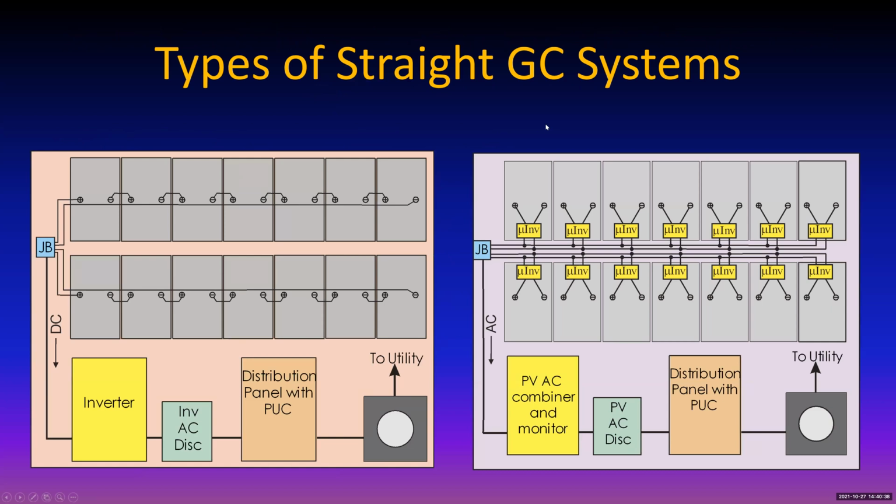Okay. So this is a string-fed inverter system right here. All right, and this is a pretty straightforward system. You notice that top row of 7 modules, and they're connected in series, plus to minus, all the way up. And then there's another row connected in series, plus to minus, and so forth.